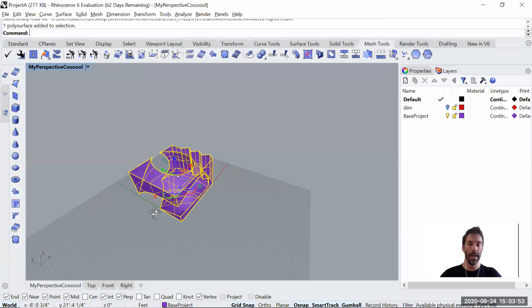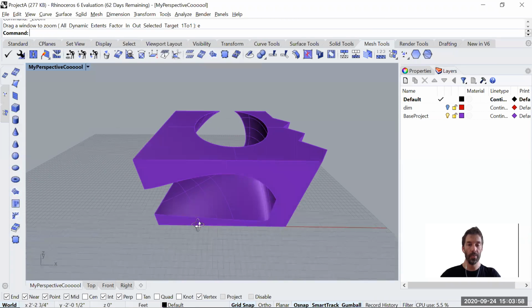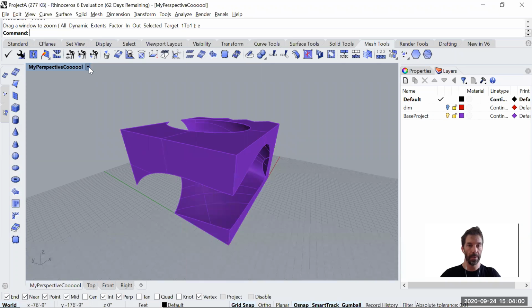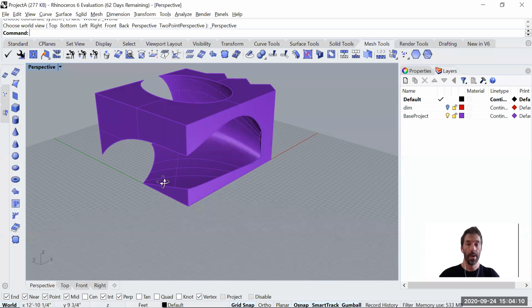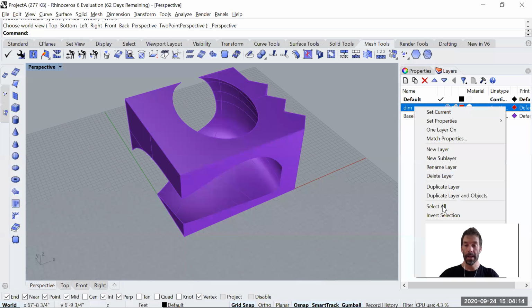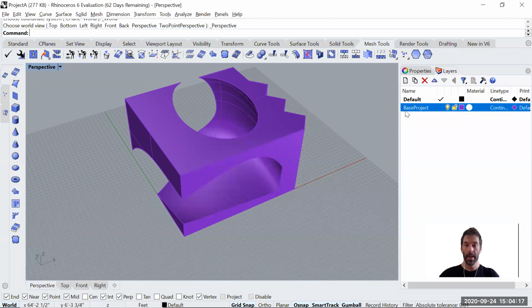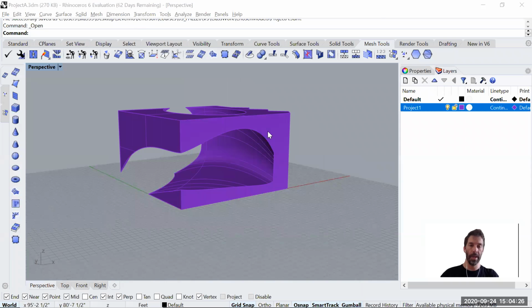Clean means that only the element that you want should be there, in the middle, and that should be at the 0, 0 coordinate, okay? Let me take this bit to perspective. You don't have to do that, but anyway. Again, 0, 0, and the scale is perfect, relates to the site that we constructed in the beginning. I'm gonna delete that layer again. And here you should rename it to make sure it's project 1, or again, Pepito or whatever it is, okay? But you should do that with the 3 of them.